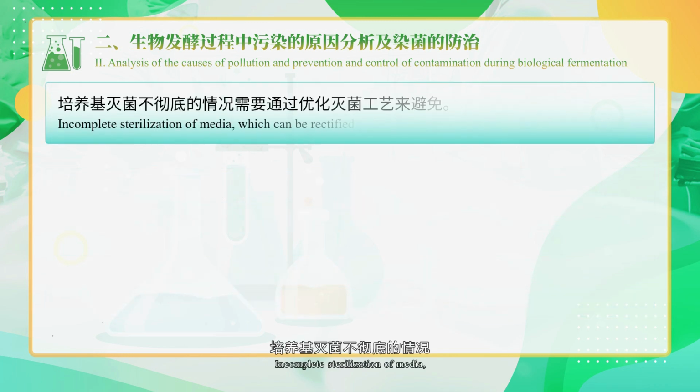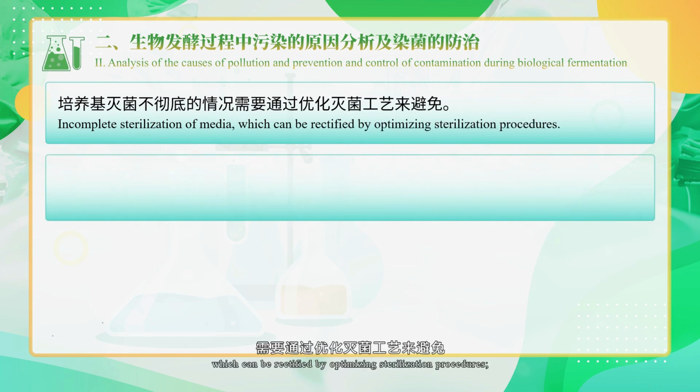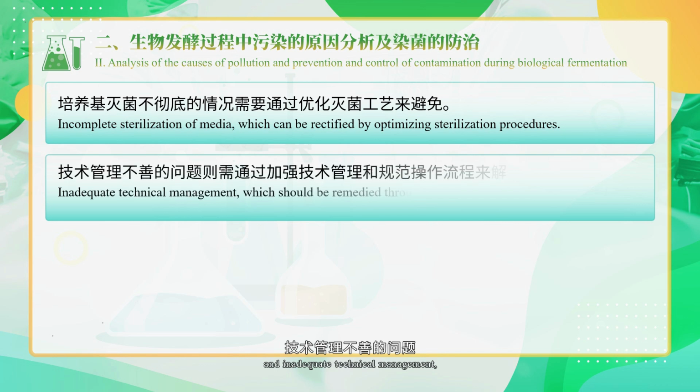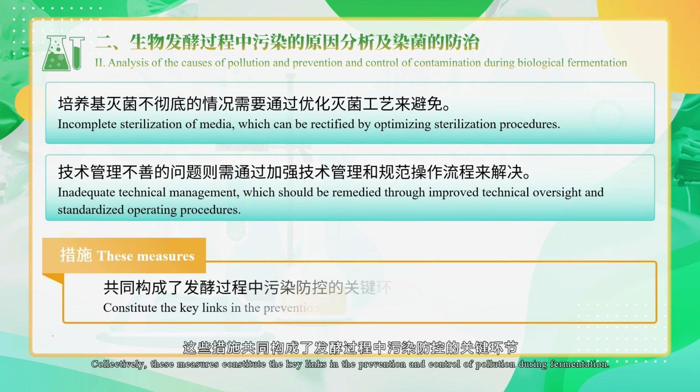incomplete sterilization of media, which can be rectified by optimizing sterilization procedures, and inadequate technical management, which should be remedied through improved technical oversight and standardized operating procedures. Collectively, these measures constitute the key links in the prevention and control of pollution during fermentation.